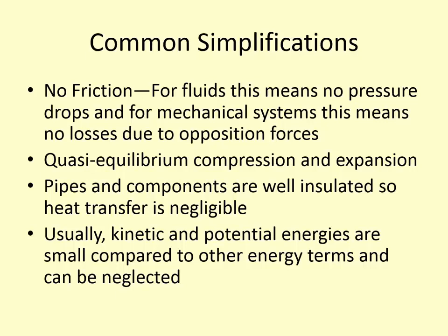Pipes and all the components will be well insulated, so we don't have to worry about heat losses. And then usually we ignore kinetic and potential energies because they're pretty small compared to any of the other energy terms that we have to consider in these processes. The kinetic energy inside of an engine is not 0 because we have pistons that are moving. However, we choose to ignore that because we're so much more worried about the combustion process and how much energy is generated from that. The kinetic energy and potential energy changes due to these pistons moving are really small compared to those terms. So we don't need to know the speed of the piston necessarily.